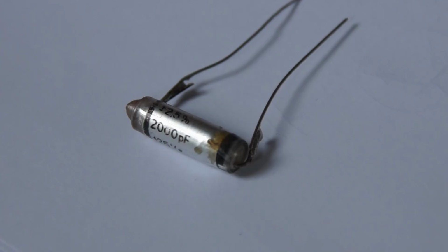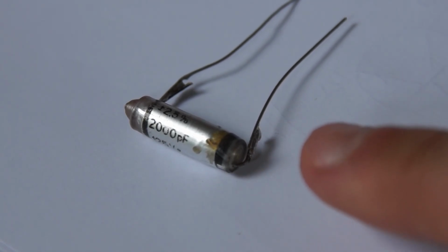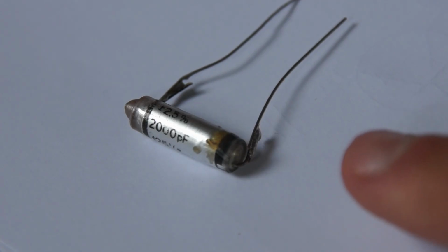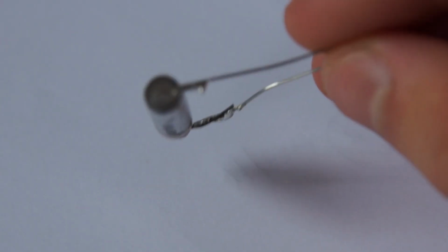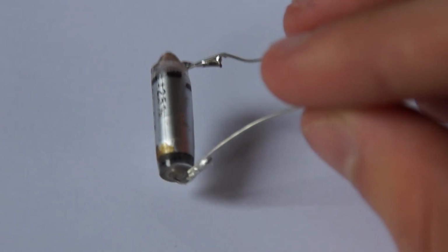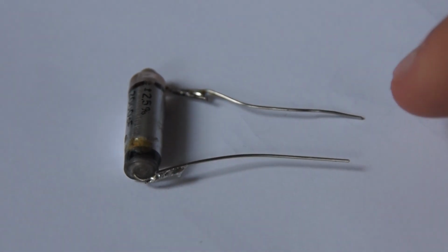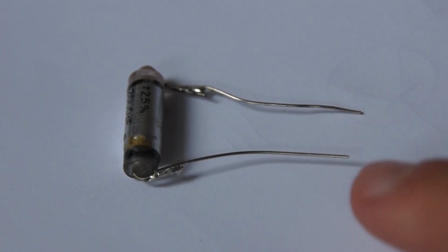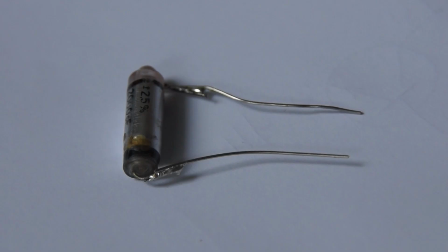The next basic electronic component we'll talk about are called capacitors. This here is a very old capacitor that I got from an old radio. What I like about this one is that you can see what the capacitor is actually made of, because they used a translucent film. A capacitor consists of two metal plates that are very close to each other but do not touch. These two pins are connected to the two plates, and so you cannot run electricity across it, but because the charges can still apply forces to each other across the plates, if you run an AC current, it actually does pull charges through.